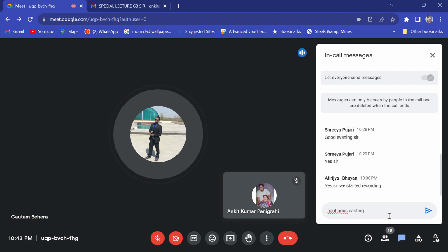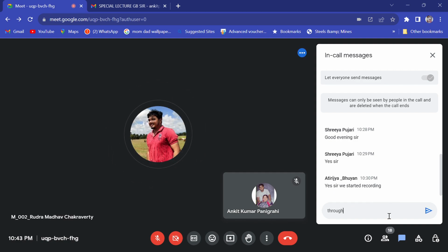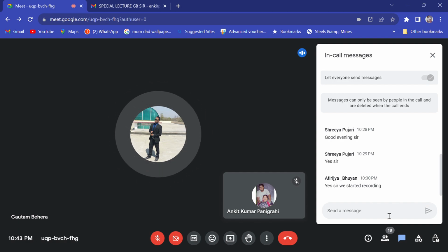Can you tell me how to remove dissolved oxygen from steels? Can you give an example? And can you tell me from where this oxygen is coming into the steel? Sorry, we are using oxygen lances. Yes, yes, good. Actually, when we are converting the iron into steel, we are blowing oxygen into the iron, then pig iron, or your scraps or molten DRIs, right?